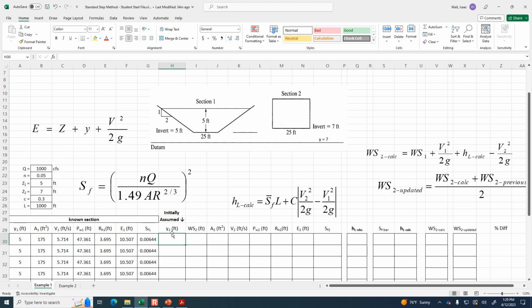What if the water depth is a little bit deeper? So let's just say 5.1 feet. I don't know how much deeper it's going to be upstream, but let's start with a little bit deeper, 5.1 feet. Okay, so water surface at 2, by definition, water surface is Z2. I'm going to anchor the reference there, and this is important because each subsequent row is going to be different, but I always want it to look up here to Z2 for the first part of the water surface, plus the depth at 2.